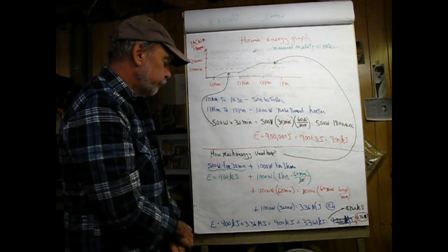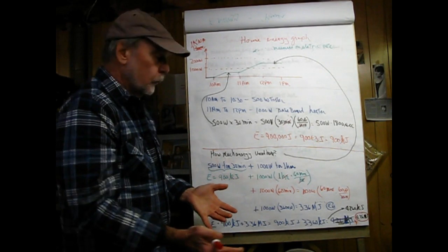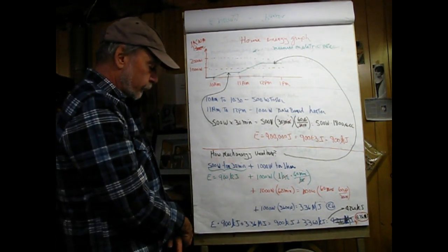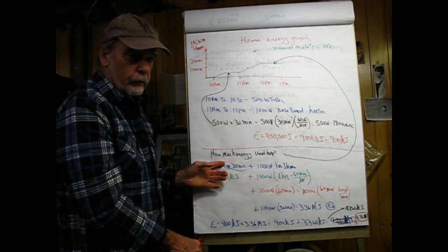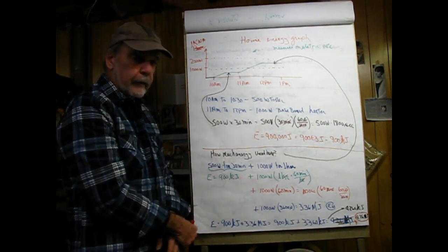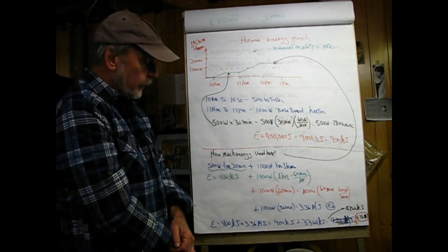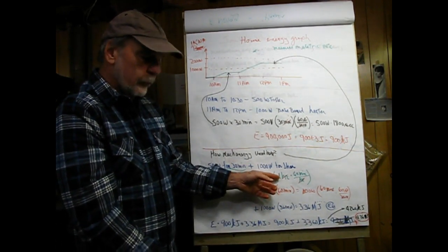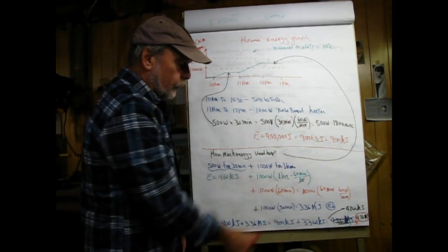So how much energy is used here in total? Well, now we have two things to calculate. First, our 500 watt toaster for 30 minutes, and the second would be the 1,000 watt heater for 1 hour. So I'm just going to write this down here as 900 kilojoules because we just calculated. Now let's go through and figure out what this guy is. So I have 1,000 watts, and I'm using this for 1 hour, and I'm going to start by converting this into minutes. So I'm going to multiply that by 60 minutes divided by 1 hour.